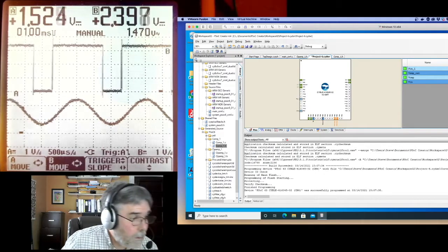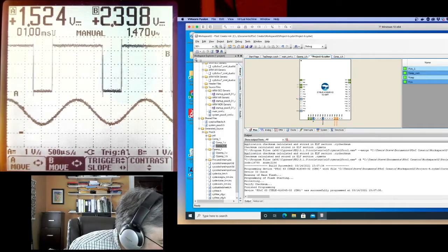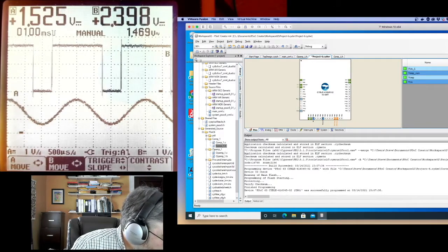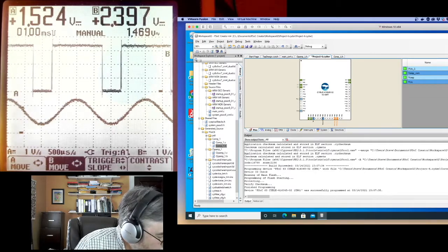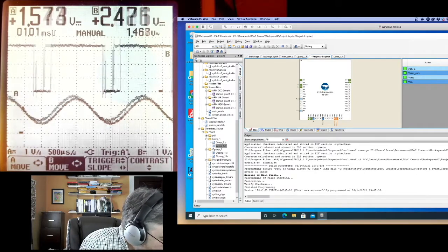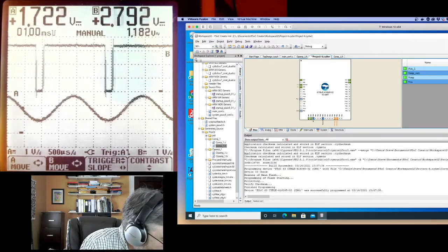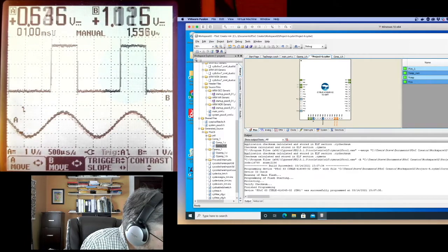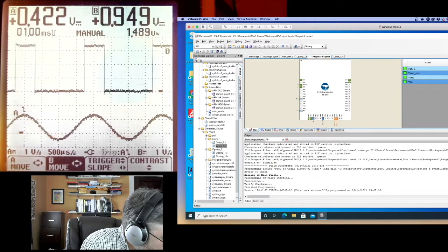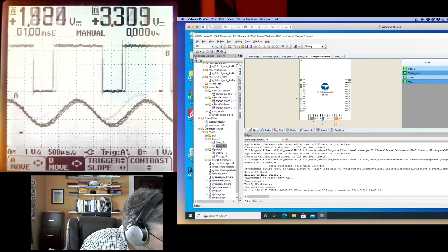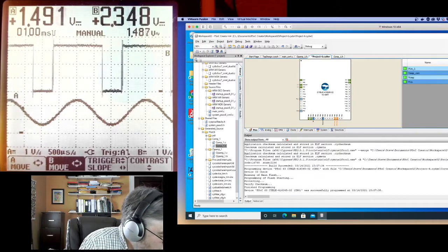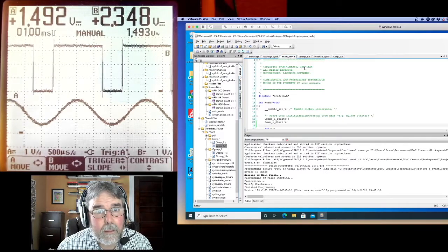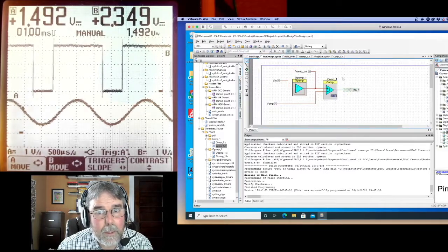And there it is. The comparator is busy comparing, and you can see that when the sine function goes below the threshold, the output goes low, and when it goes above the threshold, the output goes high. If I move the sine function up, remember it's right around 1 volt, you can see it's just passing over. Now if I bring it down, it's doing the same thing. I'm losing my trigger because I'm triggering on the sine. You can see there's a little bit of noise there, but the basic functionality is there. So I've got the op amp and I've got the comparator.